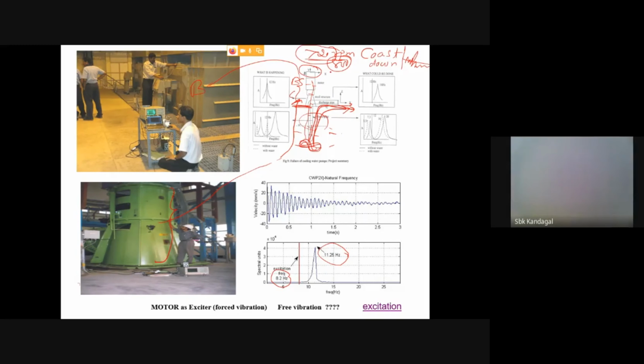So this is one of the practical ways of finding out the system properties in rotary systems. It is called the coast down study. You take it to high speed and switch it off. Any subsystem that is undergoing resonance will show up, and from that particular RPM you will be able to correlate which RPM is critical, and how to mitigate and overcome that. One cannot do forced vibration using an electrodynamic shaker for rotary systems. The only thing done in industry is the coast down study. The existing motor or generator itself can excite this rotary system by varying the speed and then switching it off.